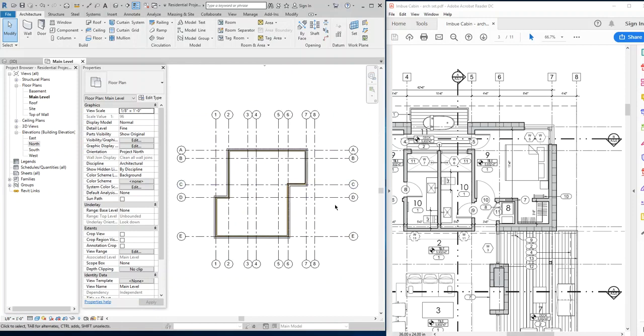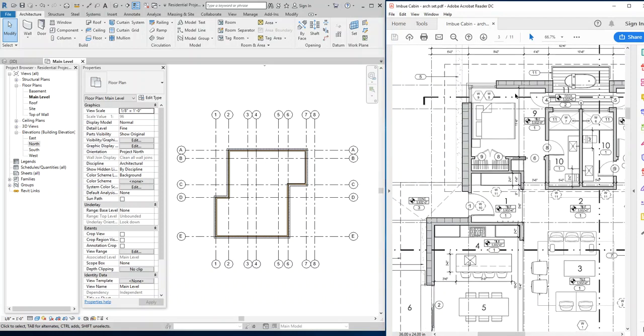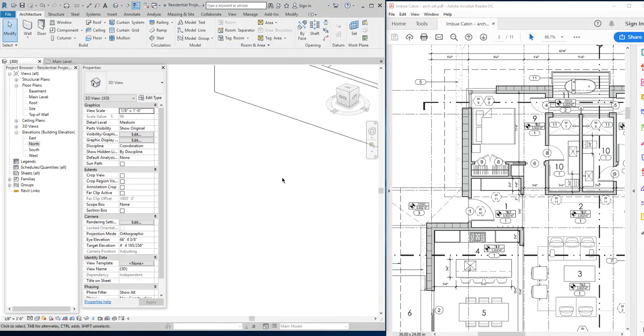And I have the outline of my space here now, right? Now that I have the outside of my space, I could start drawing the inside of my space. Although these are going to be a different wall type, right? It's probably going to be a 2x4 or a 2x6 wall with gypsum board on both sides. Okay. Any questions on any of that so far?